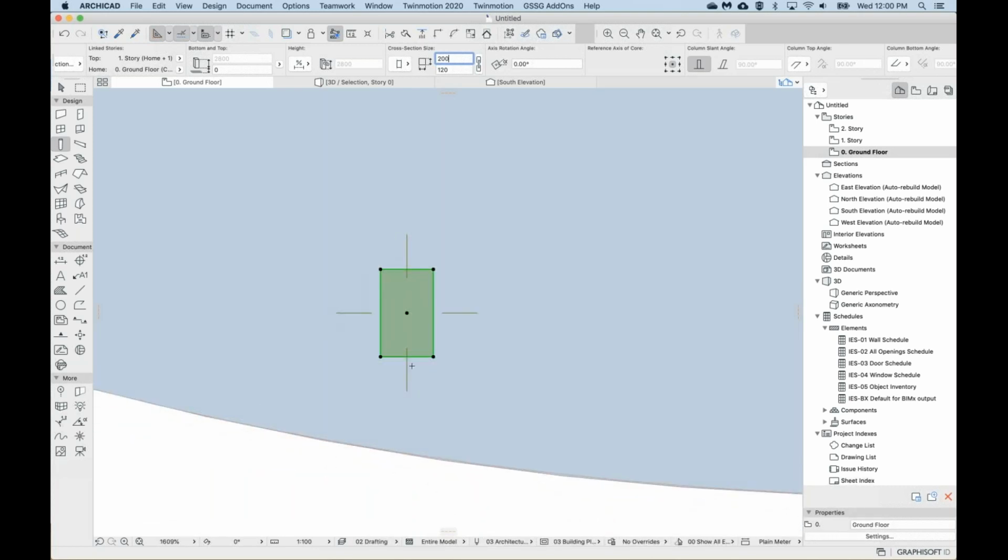Yeah, so I can see my column is still just vertical, so I need to rotate it so it's perpendicular to this edge of my shell. So I'm going to use the command Control E. This will bring up a compass, because basically I need to rotate this so it's perpendicular. So using Control E, clicking on the center point of the column, and I need to know where the rotation is from. So I'm going to click on the Y axis.